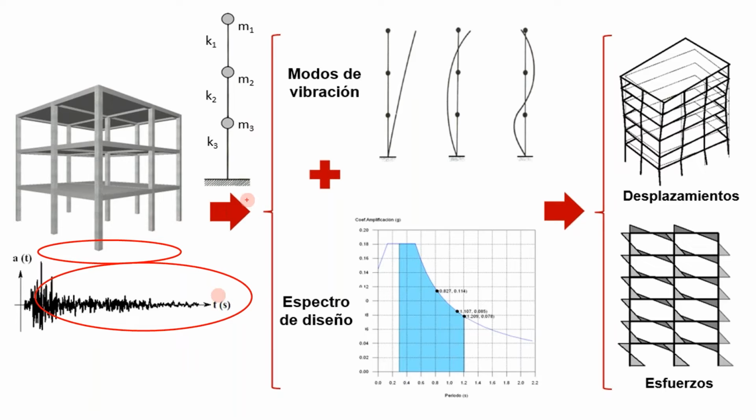By the way, we are taking into account that we are covering X and Y directions. There are some cases where we can apply 100% in one direction and 30% in the other direction. That means the simultaneity of the maximum vertical and horizontal seismic response is unlikely.